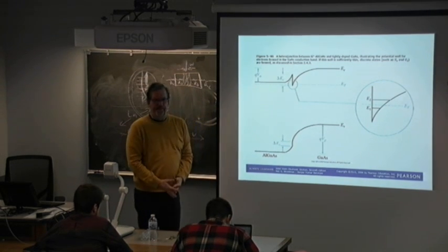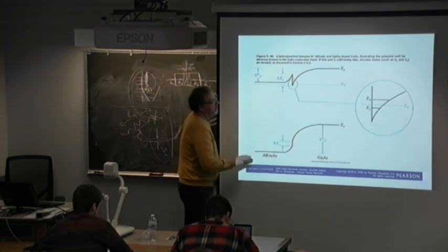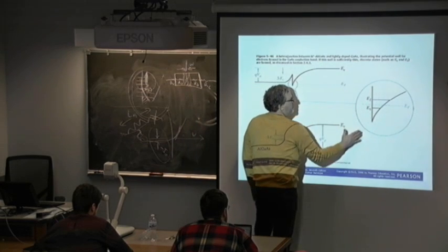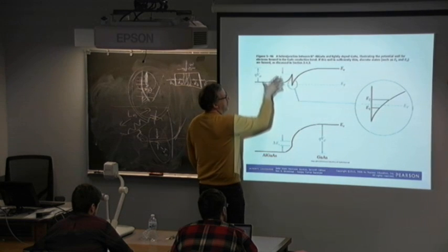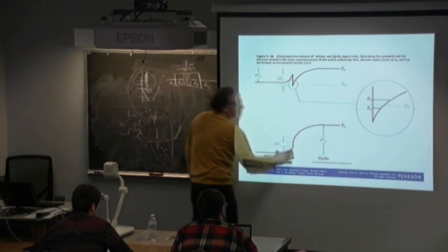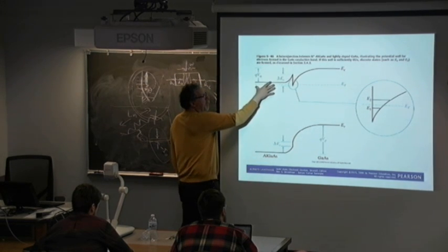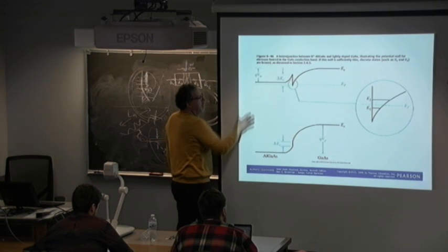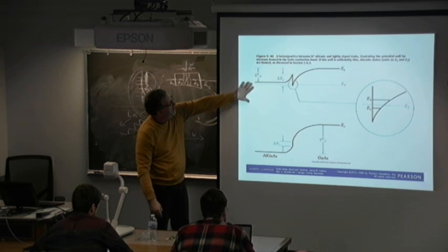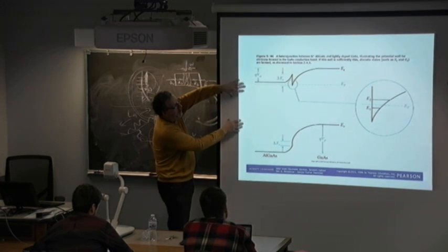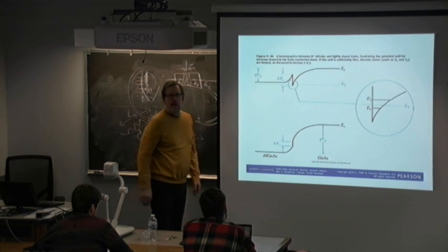So, what's your question? You say we're looking at it from the side? Yeah, I would epitaxially grow this. This would be the substrate, and then I would deposit a layer of gallium arsenide, lightly doped. I would put a spacer of undoped aluminum gallium arsenide, and then I would grow highly doped aluminum gallium arsenide, and I would have my contact out here. Probably I'd add another intrinsic layer, but that's getting too complicated. And I put my gate up here, and so yeah, this would be the top.